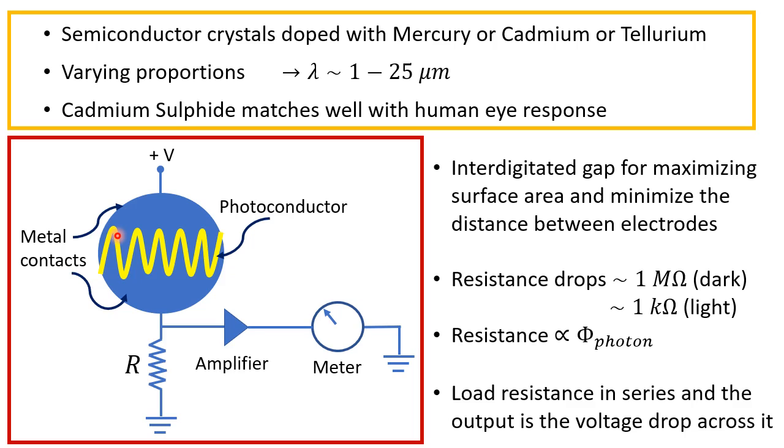You see that the carriers are being generated within this yellow thin sample, if you like, and these carriers need to propagate to form a current, for example, from the positive to the negative. And if this material is significantly large, those carriers will be lost due to recombination. We will talk about this in a little more detail, but the idea should be clear that we want to make this material reasonably thin so as to not lose the carriers that have been generated as a photo response of this material.